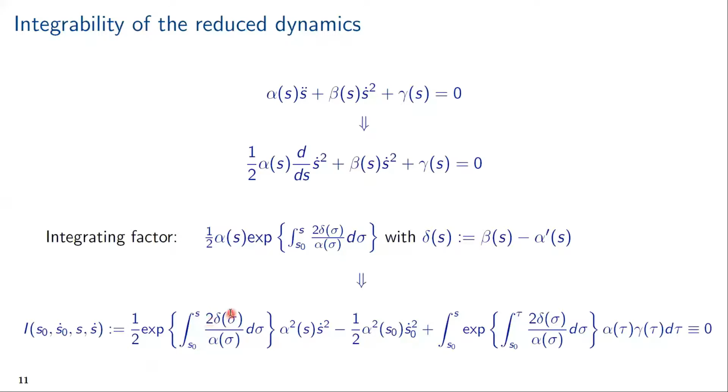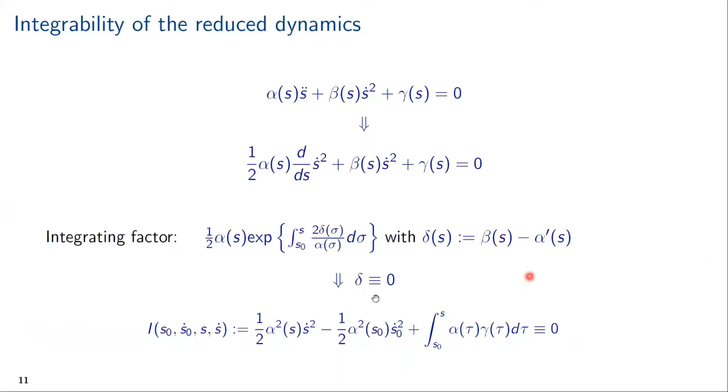Luckily, for some types of systems, especially underactuated systems in which the first generalized coordinate in a kinematic chain is passive, so unactuated, delta goes to 0. This will, for instance, be the case for the joint describing the ankle of a biped walking robot. So for this, we might set delta equal to 0, and we have a quite a lot simpler expression.